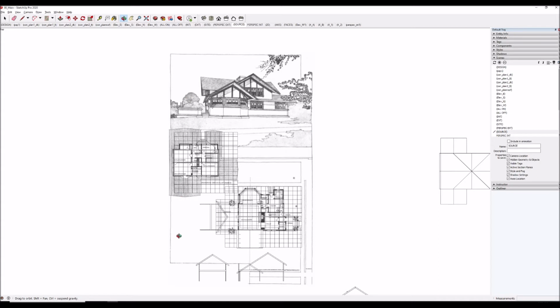Here's that image that I've imported into SketchUp, and I have to figure out the basic structural alignments of the main elements, like the roof here. I've noticed that this roof is one continuous slope. There seems to be a break here, but that's just perspective, because this angled piece is coming forward. So due to perspective, it looks like there's a break in the roof line. But actually, from the ridge, it's a continuous slope all the way to the eave here. And it starts on the second floor and ends on the first floor.